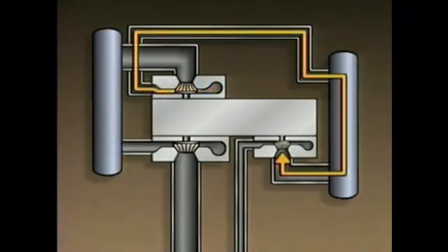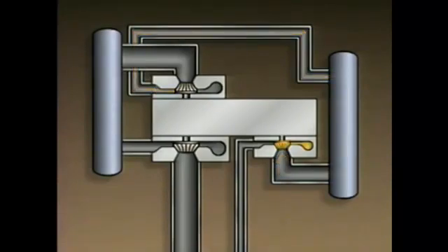The gas is cooled by a second intercooler and then directed into the third impeller and third volute where its pressure is increased again. When the gas finally leaves through the discharge line, it's at a much higher pressure than it would have been with only a single stage.